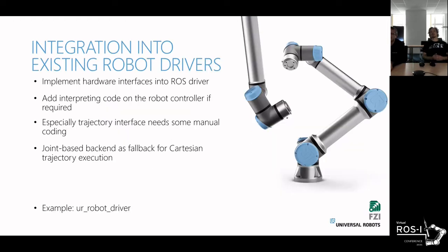Yes. Great. So the question is how to integrate this into your existing robot driver, as it was all developed with the robot driver in mind, and it's integrated into your robot driver. However, we explicitly wanted to design this robot driver independent. I mean, it's just a ROS control extension, so you can include it in every existing ROS control driver. You just have to implement a couple of hardware interfaces, as I've described before.